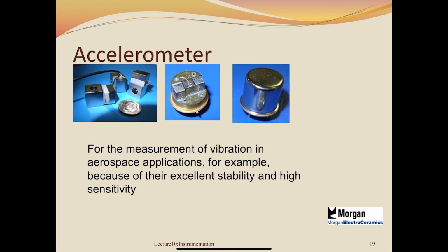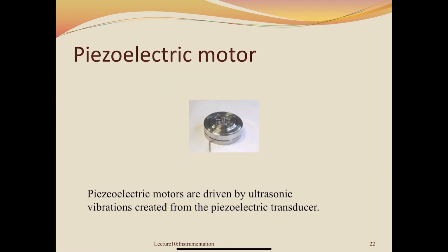Second application of piezoelectric is accelerometer. So, accelerometer is a sensor that is used to measure vibration. The accelerometer uses the piezoelectric material in the housing that acts as a seismic mass that will convert the acceleration to force by the equation F equals ma. Next is the piezoelectric motor, where these piezoelectric motors are driven by ultrasonic vibration created from the piezoelectric transducer.